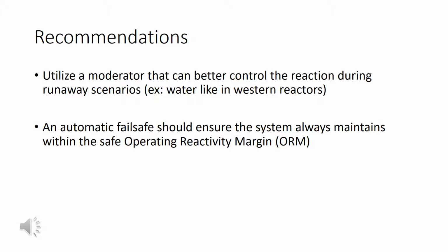My second recommendation would be for an automatic system to ensure an adequate operating reactivity margin is maintained. The ORM is manually controlled by the operators, who did not understand that in an effort to increase the output of the reactor following an unintentional cooldown, they raised the control rods and did not maintain a sufficient number of control rod surface area in the reactor to account for the conditions.